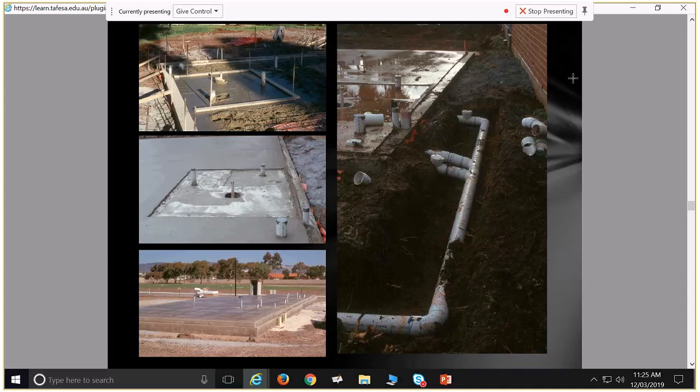And that set down happens in your concrete by, you pour that section first, and then you put out some timber boards, stake it with some steel pins, etc. So it starts going off a bit, and then you build up your concrete higher around it. So it's not like you chop concrete out of there, you just pour that section first, your low section first, and then pour your high sections later.